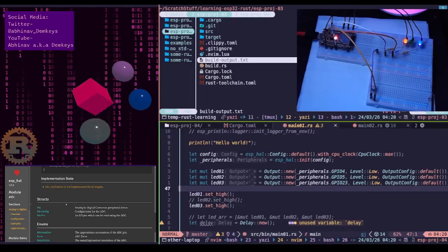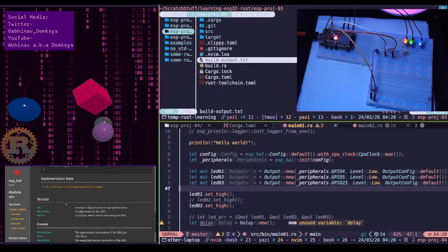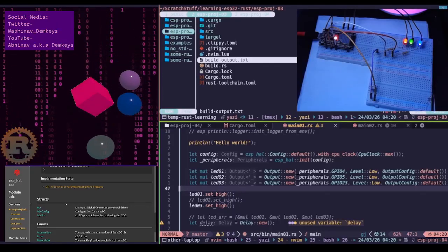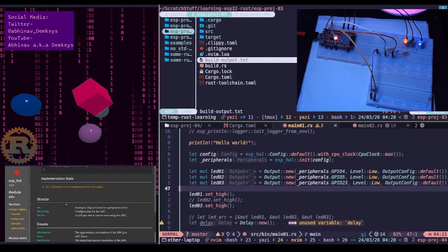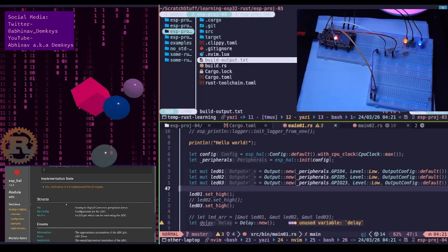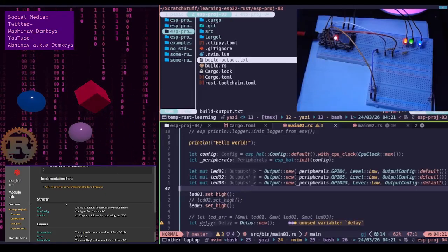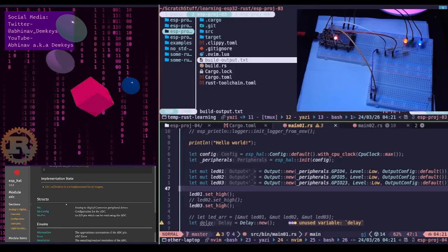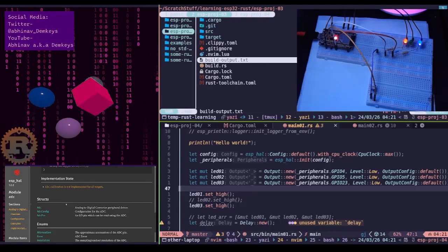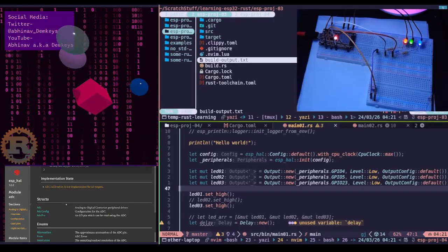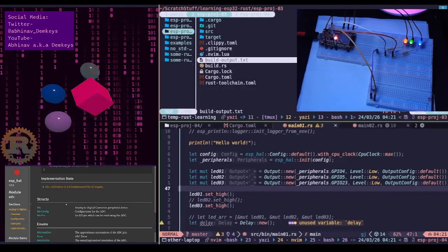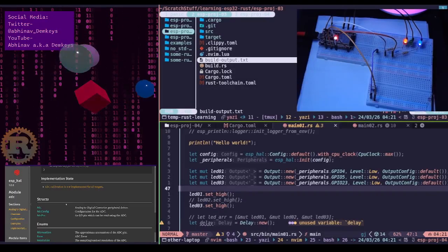Okay, dead zones. On the original ESP32, the ADC is blind below 0.1 volts. You might connect a pin to a very weak signal and get zero back, leading you to think your wire is broken. Verdict: if you are just learning how to write no_std Rust, skip the calibration for now. Focus on the HAL, the registers, and the async/interrupt flow. Just keep a mental offset that your numbers are ballpark figures, not scientific measurements.